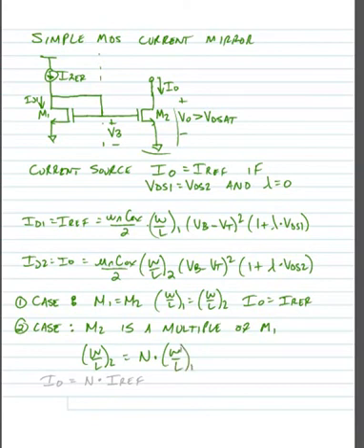And we do this simply by making transistor M2 larger than transistor M1 in the width dimension. And if we do so, we would note that our output current, I0, would equal N times the reference current. So this is a nifty way to generate multiple different currents with different amplitude levels across the chip simply by changing the ratio of the device's geometries.